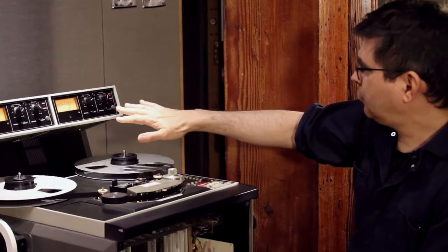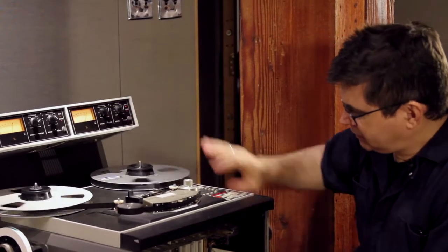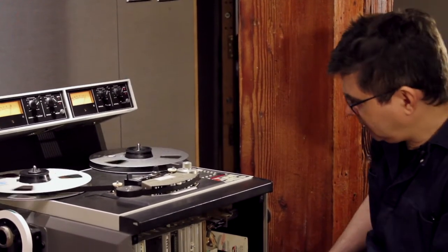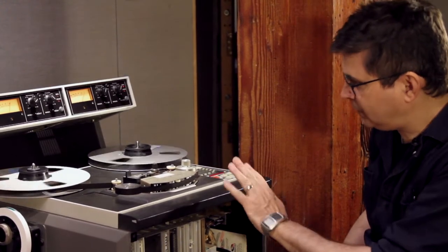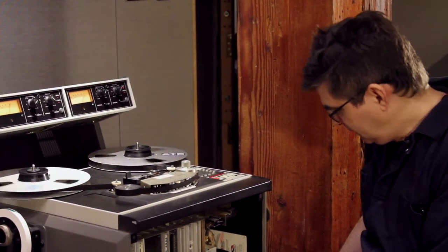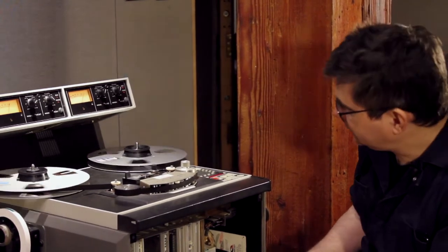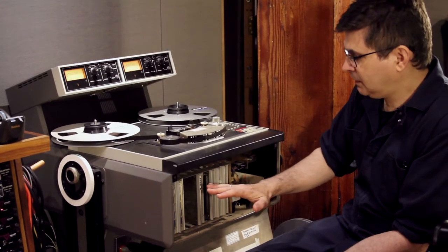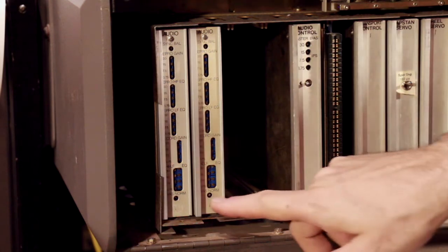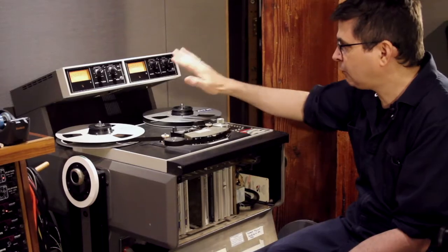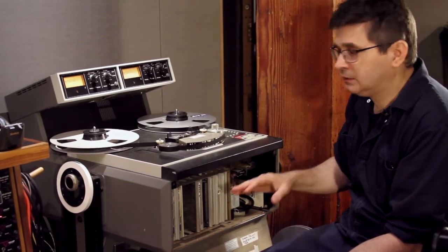Okay, so I'm recording a 20 kilohertz tone on the machine here, and I'm going to adjust the bias to correspond with our in-house standard, which we've derived from the noise performance of this machine. And our in-house standard is 3 dB of overbias at 20 kilohertz. So for this alignment, I'm going to use the master bias control to align the left channel, and I'm going to use the individual channel control to align the right channel. And then the next time I align the machine, I might do it the other way around.